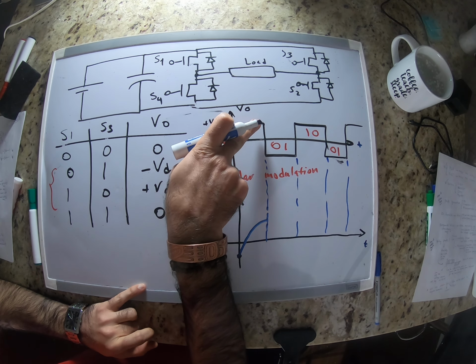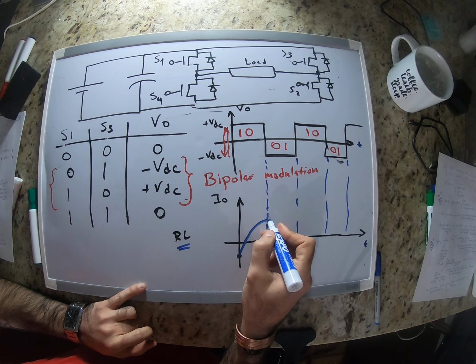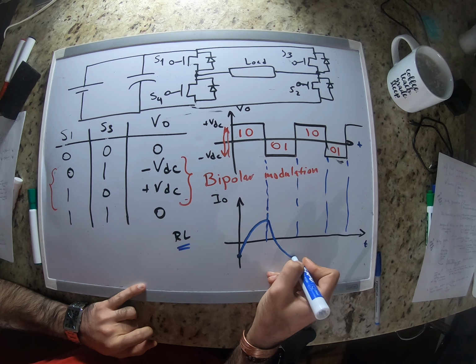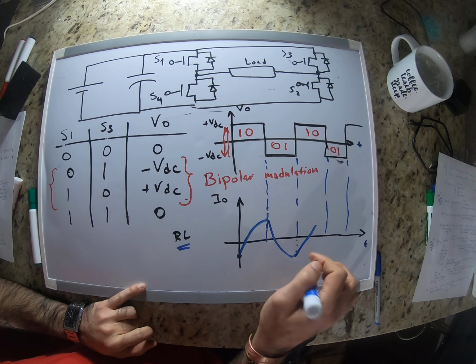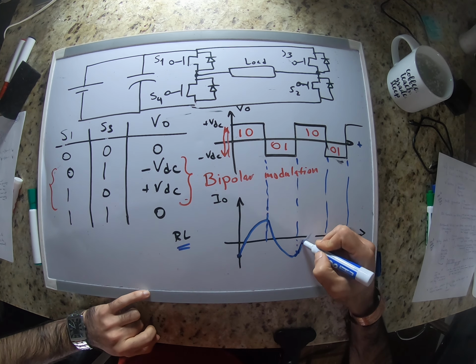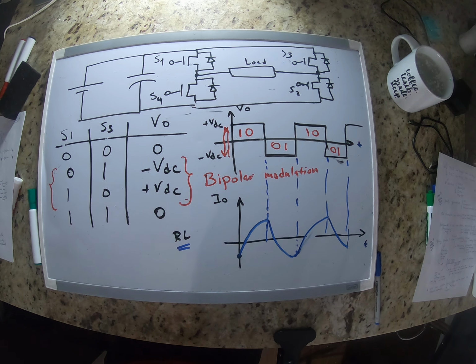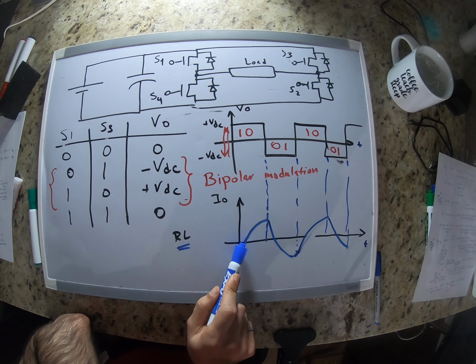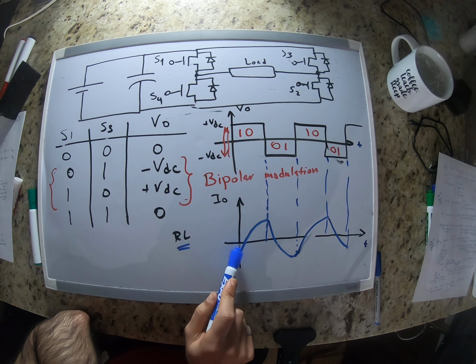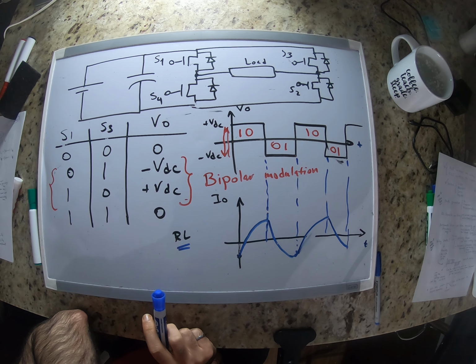But you see here, it's increasing, and as soon as it hits this point, the voltage changes. So now it starts decreasing. And again, it starts increasing, decreasing, and this would continue. So you can again see that we're going to have different quadrants here. You see that current can be negative, voltage positive, and what we discussed about the reason to have anti-parallel diodes.